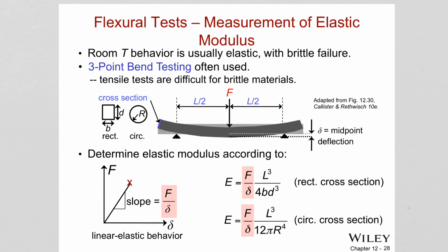This is due to the fact that if there is a crack present and we apply tension, this crack will have stress concentrations and will propagate. But if you do it under compression, it will not build up stress around the cracks. You are actually closing the crack, so it's not propagating. So under compression they are strong. Under tension they are weak.